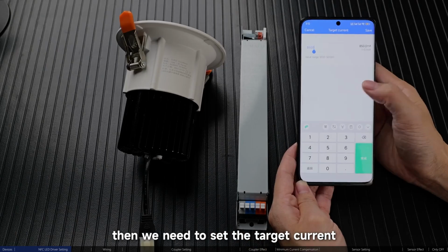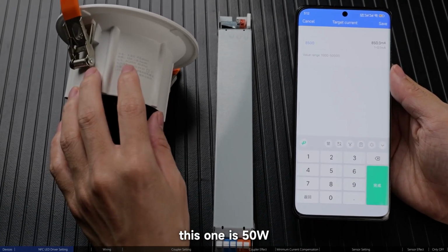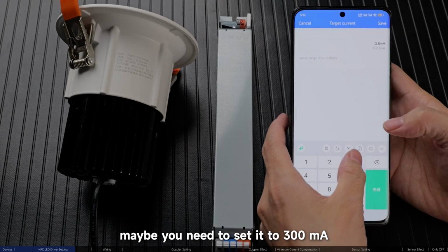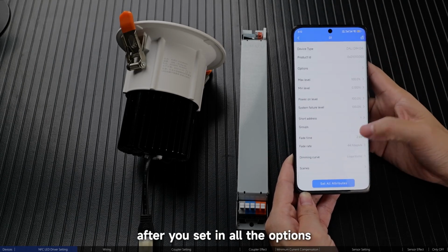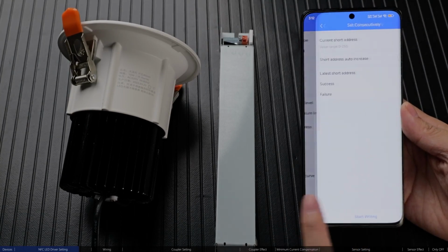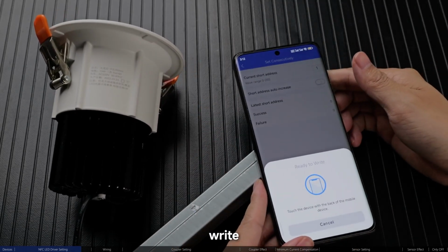The important option is the target current. Click it. Then we need to set the target current for the LED lighting power. This one is 50 watt. And maybe we need to set it to 300 milliampere. Okay, save. After you set in all the options, click set all attribute. And then start writing.